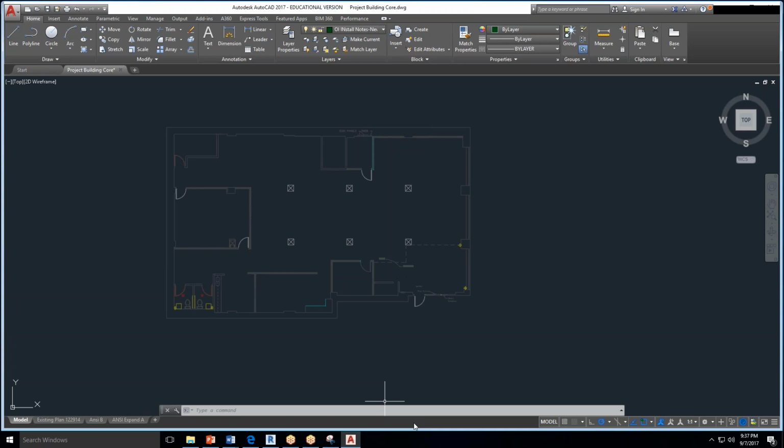No, you don't need an option to pick roof. A couple people talked to me about this. When it's asking you level 1 or level 2, it's asking you the ceiling height of the level it's connecting to. So it's actually saying the roof is going to become level 2, because we don't have a second story. Level 1 is everything from the ground up to the top of the wall.